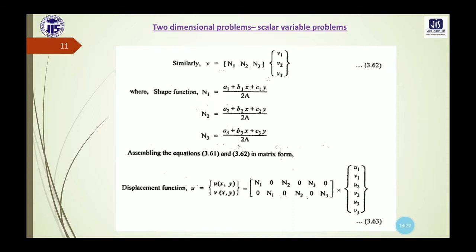So this is the final equation of the displacement function, where we need to remember the shape functions, like N1 is a1 plus b1x plus c1y divided by twice a. Again, we need to remember the formulas of a1 and b1 in terms of the coordinates x1, x2, y1, y2 to solve different numericals.